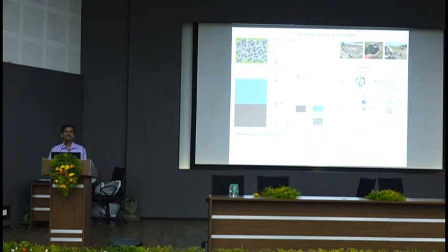So then one student became successful because he was adding very small things and getting only thermal and electrical properties. But suppose you are interested in some other properties like liquid limit, plastic limit, you need more samples. So for that, we tried to culture one bacteria called Xanthomonas campestris. That was a difficult term, but they say it produces xanthan gum and it is available in the market. Obviously we have no time to make a culture, but we were fortunate to have a life science department. So there we made the culture and got lots of bacteria, I mean that polymer.